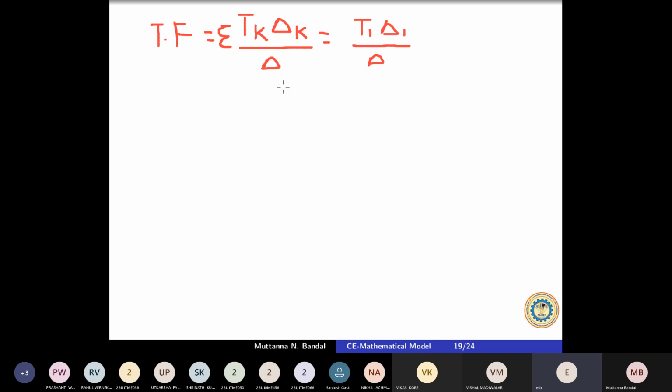Now let me calculate the transfer function for this. What was the value of T1? I told you to make a note of it: the product of the forward path. G1, G2, G3, G4. So I will write it as G1 G2 G3 G4. Now I got this term.